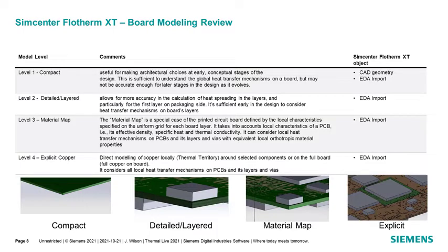This table outlines the common modeling approaches for printed circuit boards, but also discusses a couple methods that are unique to Simcenter Flotherm XT and FloEFD. And on the left-hand side, modeling level column, you see we go from level 1 to 4 and the different modeling approaches. And on the right-hand side, the information that you have available or the information that you would import into the tool.